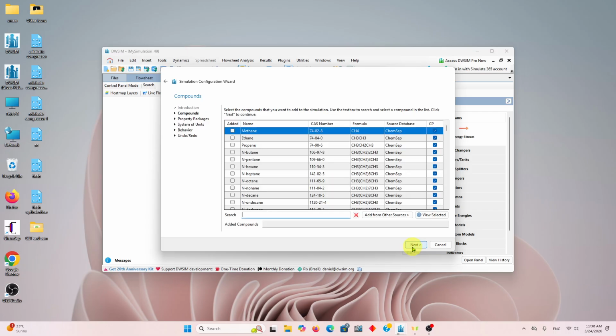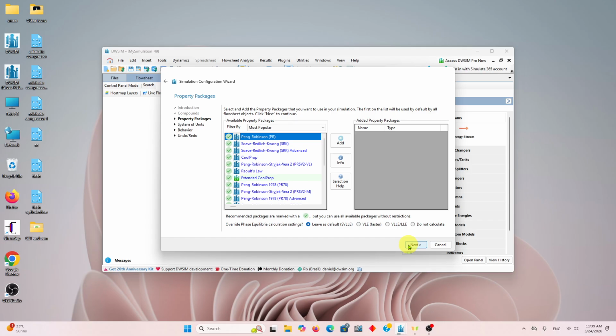So you need to insert a component. n-Butane is the component, and it is already visible here, so you don't need to search for it. Then comes the property package, one of which is Raoult's law. That means if you want to find out the ideal molar volume, you have to use Raoult's law. And if you want to find out the real gas volume, there are a number of methods. One such method is the Soave-Redlich-Kwong (SRK) method. So these two are selected at this moment, and the rest of the things keep as they are.